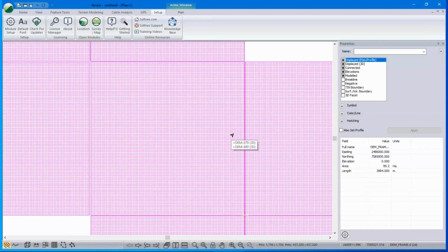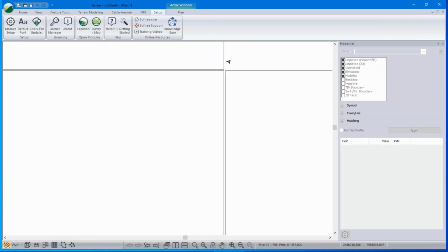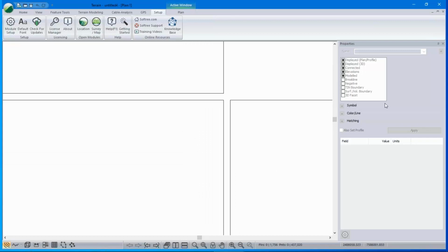So if we zoom in on this and take a look, by the way, when you do file insert, it always selects all the points. So often the first thing you want to do is just hit cancel or click somewhere where there's no data, so you don't have this large number of points being drawn. But anyway, here's my tiles.